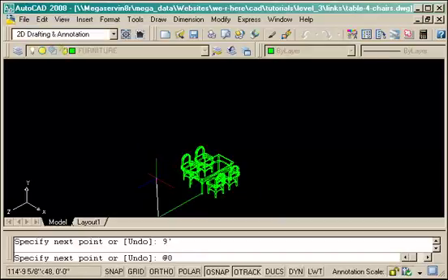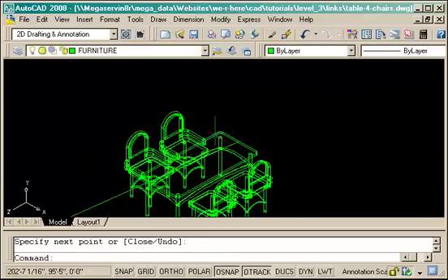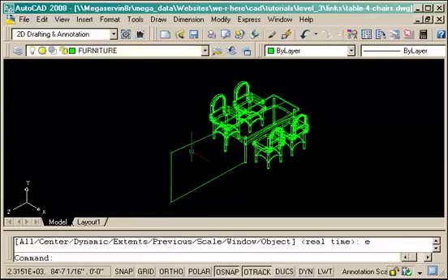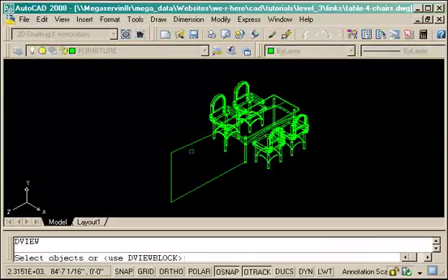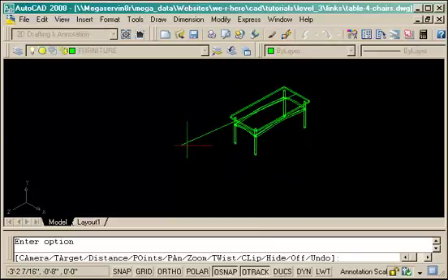But before I do that, I have to start up and create some lines. I've gone 9 feet away from the table, 5'6" up, and I'm creating a line of sight that goes from, say, an average person's height looking down the table. So I start the dview command, I select the table, and I select my line, and you'll see why I select the line in a moment.